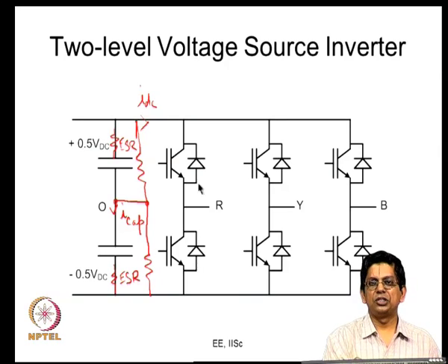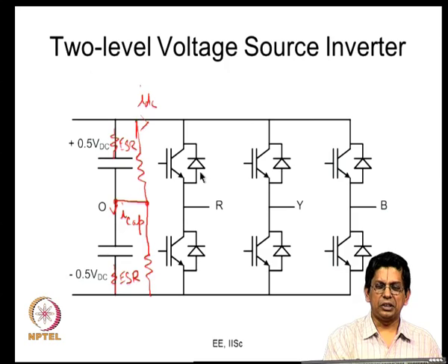You may have large heat sinks. Sometimes the devices may be mounted simply on heat sinks, sometimes on heat sinks with air blown between the fins, which is called forced air cooling. So, there is natural air cooling and there is forced air cooling. You have certain cooling arrangements, but even with them, you have to make sure that the device junction temperature does not cross something like 120 degrees Celsius, which is taken as the safe junction temperature for many of these devices.